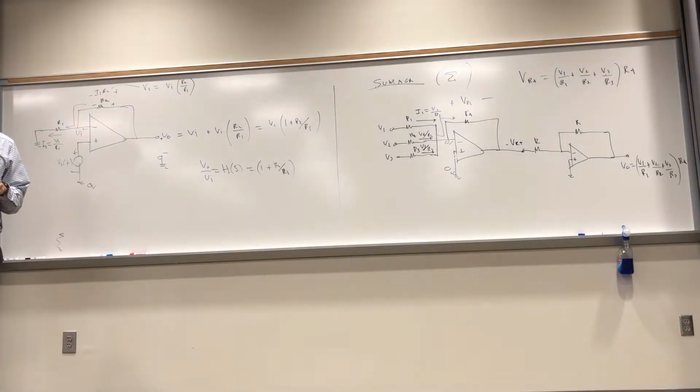Like so far, the op amps, the two terminals always share the same voltage. Is it always going to be like that? The voltage difference between the plus and the minus is 0. So whatever voltage is at one terminal is at the other in the ideal op amp. That's the way it works, and that's the basic law. There's no current into it, no voltage across it. And it's done by all sorts of feedback and things like that that have to do with the internal workings of the electronics that I can't get into here.